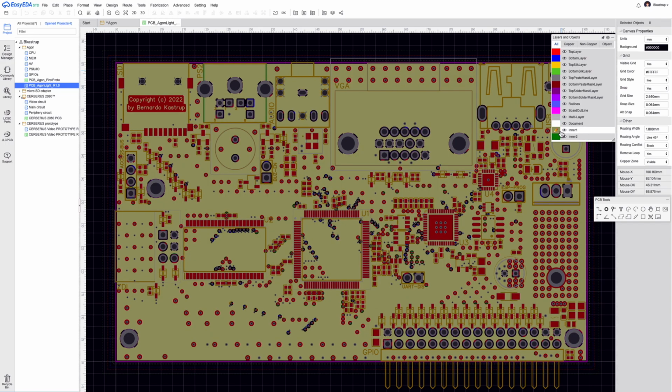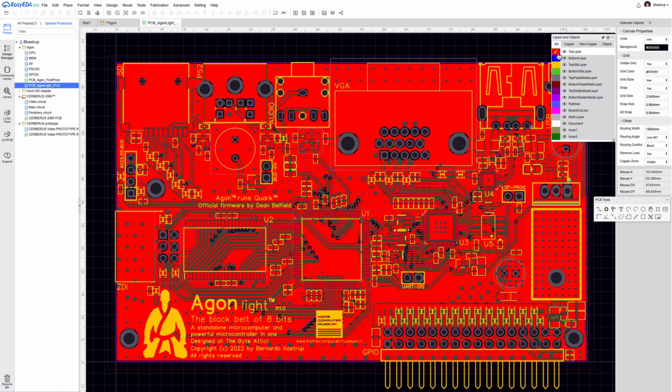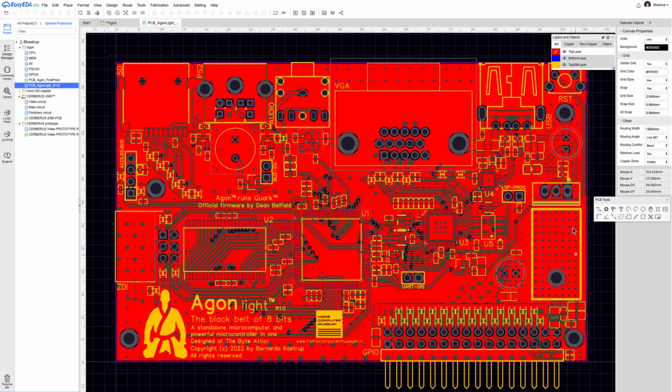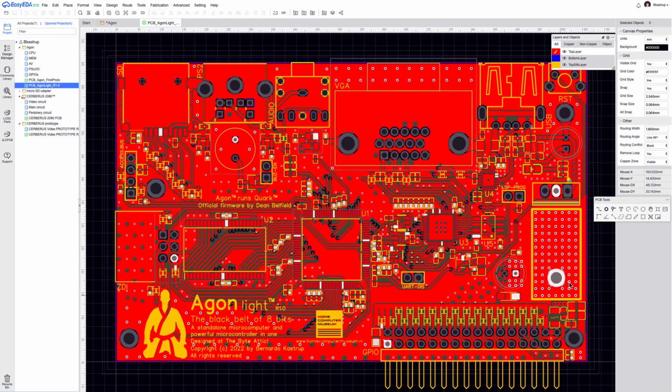And then you might ask, well, why don't you just change the order? You make inner 1 VCC and inner 2 ground, and then they are all close together. Well, then you lose that effect of a capacitor, because I copper flooded everything at VCC here. It also helps give me this large area here to connect 3.3 volts coming out of the regulator to a lot of metal space here.